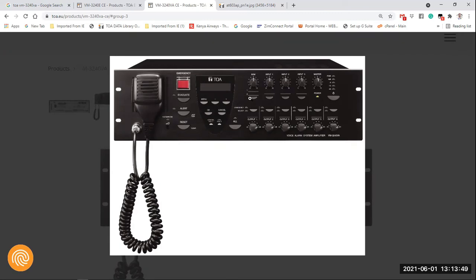You can only play one or the other. I'll repeat. With a VM3000, when you have 2 music sources connected, you cannot play both of them to 2 different outputs. You can only play one music source to one output at any given time. This is why you have a BGM 1 and 2 select button in front of the VM3000.